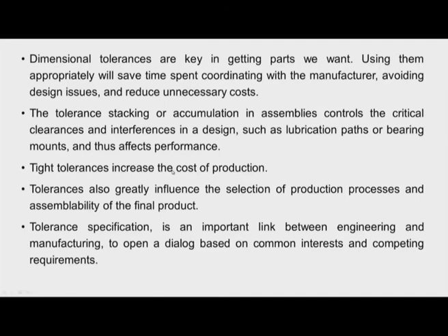And we should understand that tight tolerances will always increase the cost of production, and they will also influence the selection of production processes, and the assemblability of the final product will also be affected. So the tolerance specification is an important link between engineering and manufacturing departments, and opens a dialogue based on common interests and competing requirements.